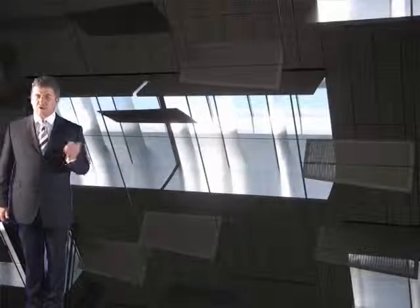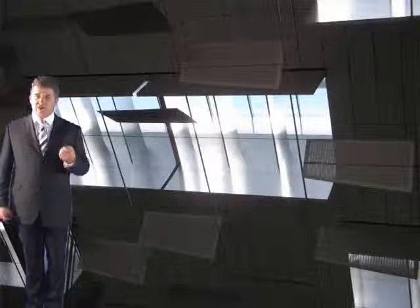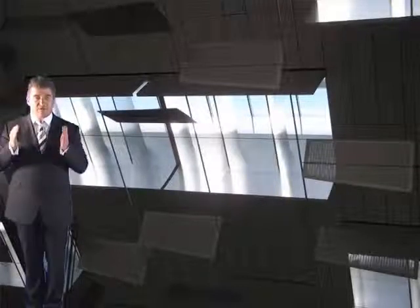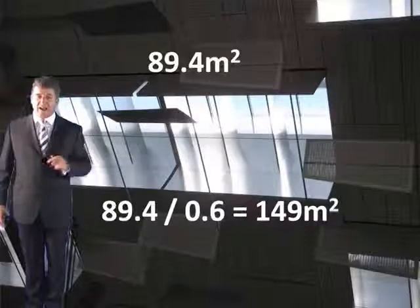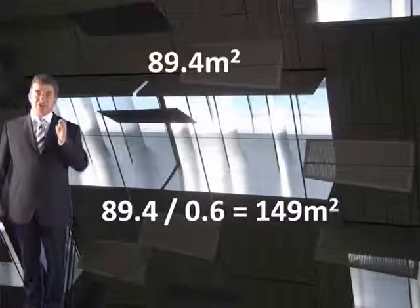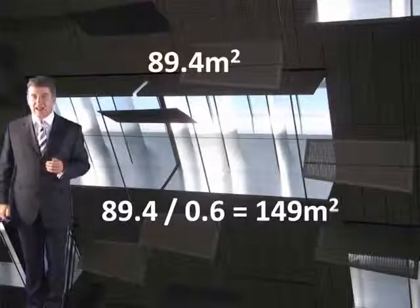So, we know what total area ventilation is required. Now, this is aerodynamic free area. In other words, you've got to take into account the coefficient of the ventilators, because ventilators are not totally efficient. So, what is the ratio of efficiency? Generally, the coefficient for efficiency is 0.6 for most ventilators. So, if we divide that by 0.6, we need 149 square metres of geometric area from the ventilators. Do you understand? That's what we actually need in geometric area, in physical area.